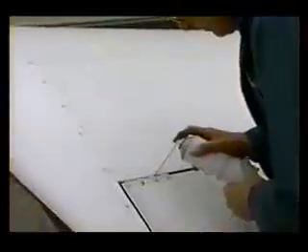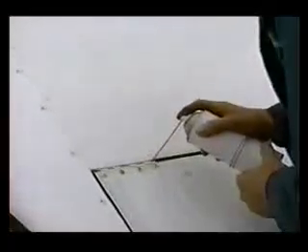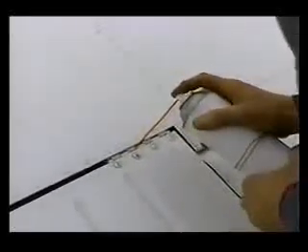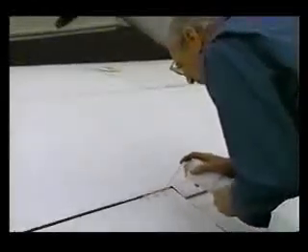Piano hinges are prime spots for corrosion due to contact between the steel pin and the aluminum hinge. They are also natural traps for dirt, salt, and moisture. Rarely used hinges will often corrode and freeze closed. To prevent this, they should be cleaned and lubricated during each inspection.